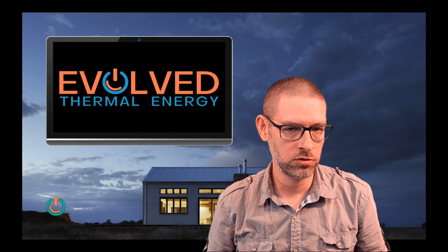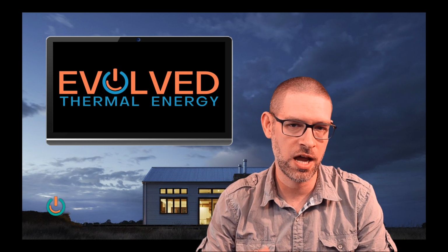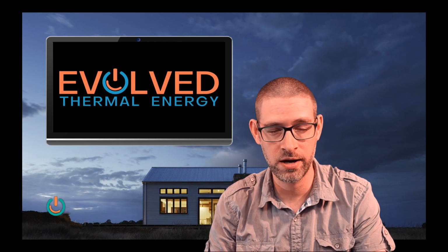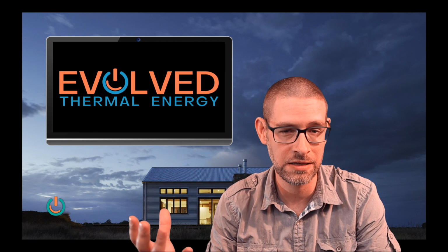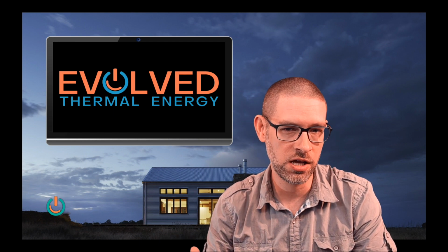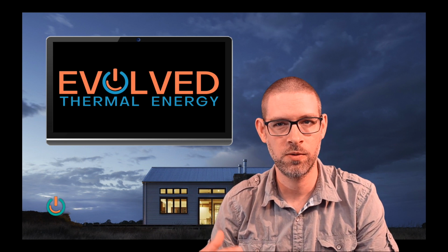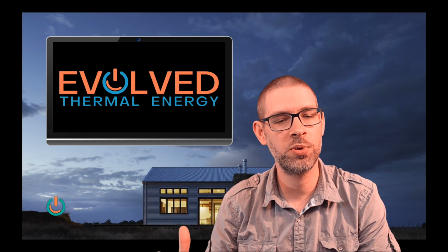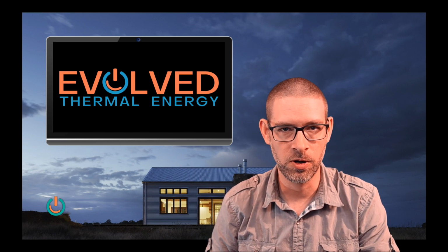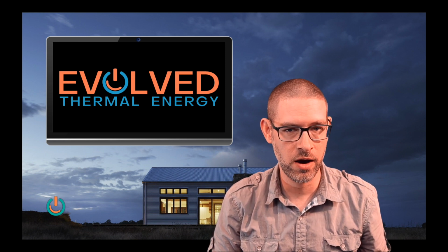With a geothermal heat pump connected to a ground loop, the electrical energy I'd actually have to buy from the electrical grid to provide 33,700 kilowatt hours worth of thermal energy to the home is only about 8,800 kilowatt hours. The rest of the energy is coming from the ground loop, right? That's that free thermal energy that we're extracting from the ground. So this equates to a COP of 3.8, so that's 380% efficient, well within that range that we had talked about. So again, I'm only paying the electric utility for 8,800 kilowatt hours of usage.